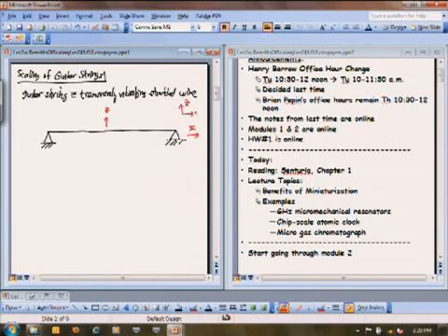Okay? So that's one of the conditions of this simple support. But you'll notice that I'm not really constraining this string in too many other ways. So as this string starts vibrating here, and so let me show a little bit of vibration, it's going to take on a mode shape that might look like that. As it vibrates, I'm not constraining the angle, for example, that this makes with the support. Right? That's an unconstrained thing. So that's part of the properties of a simple support as well.